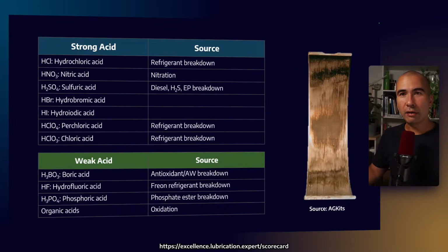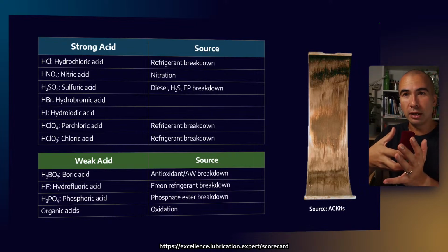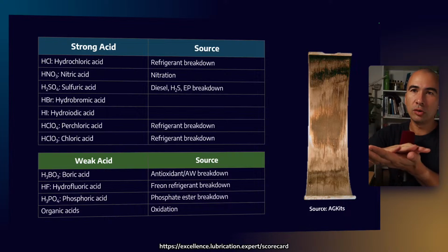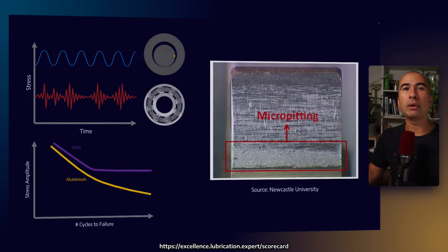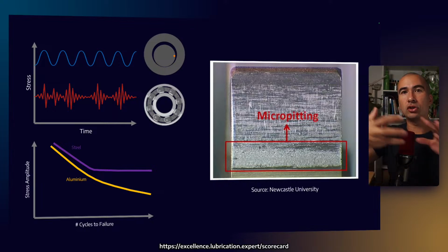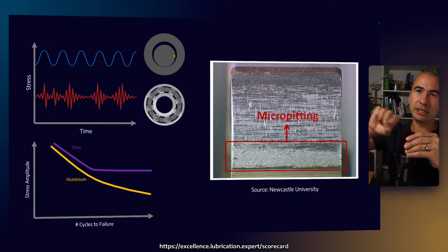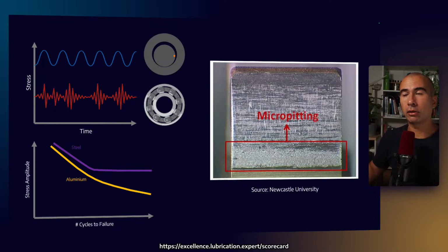We also have corrosive wear. When we have the buildup of acids, which then corrode surfaces, it makes them softer, which means that they are more likely to be rubbed away. So it's accelerating the wear process. And we also have fatigue wear. When we go through cycles of loads, eventually what we get is crack formation and crack propagation. When the cracks join up, they basically shoot out a small pit of metal, and so we get something like micro pitting.